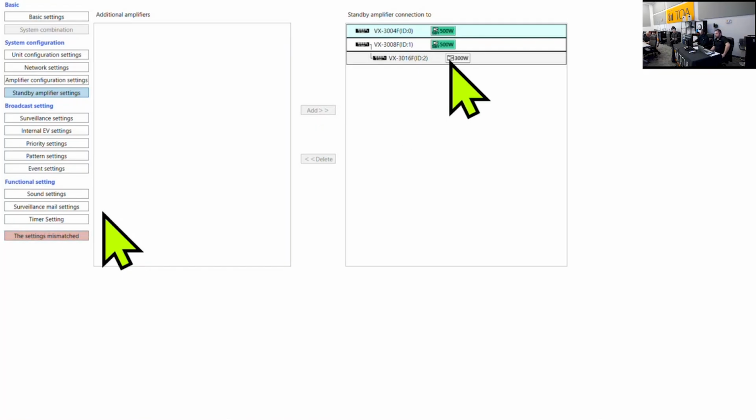It's under the assumption that once one fails, you go out of your way to get that going again, because you could have up to 8 amplifiers set to 1. So if one fails, you want to make sure nothing else fails during that time, because if another one fails, you only have one standby amplifier connected to that one frame. So then those other zones will be out of luck until that gets replaced.